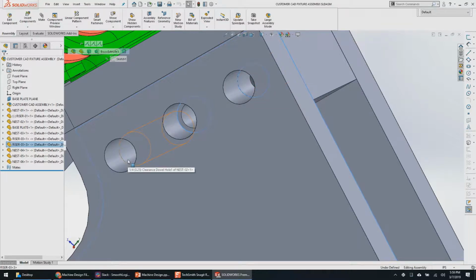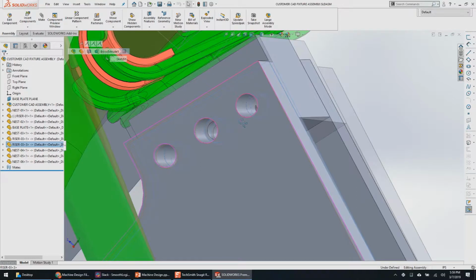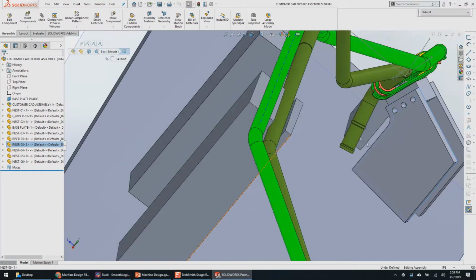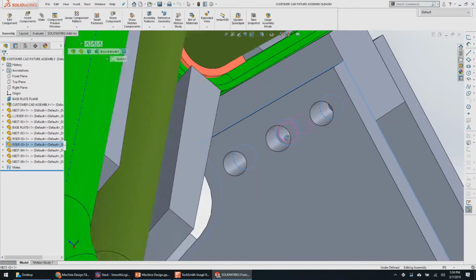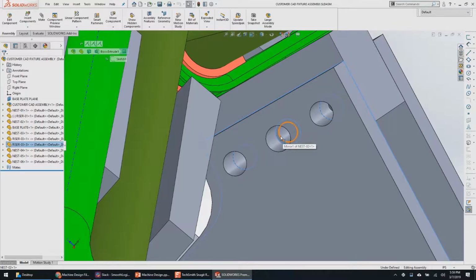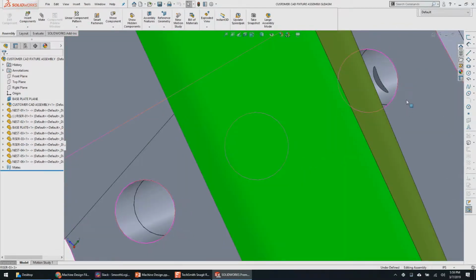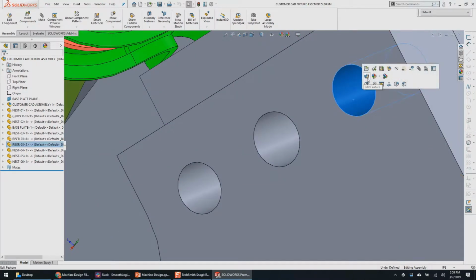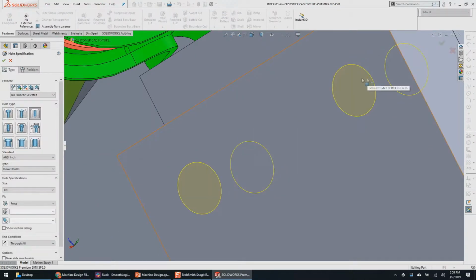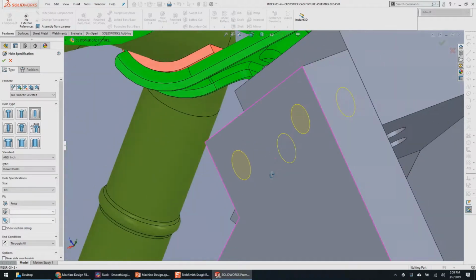So I think these two outsides are dowels. So it's a 1/4 inch clearance dowel through the main block. I think we talked about that a little bit. We clearance blocks that are blind so that we can slip them in and out. And then we do a press fit on our plates so you can pound them in and out. And that's kind of the rule here. In this instance, you only need 2 dowels and one bolt to hold it in place because the dowels are alignment, bolt is just clamping force.